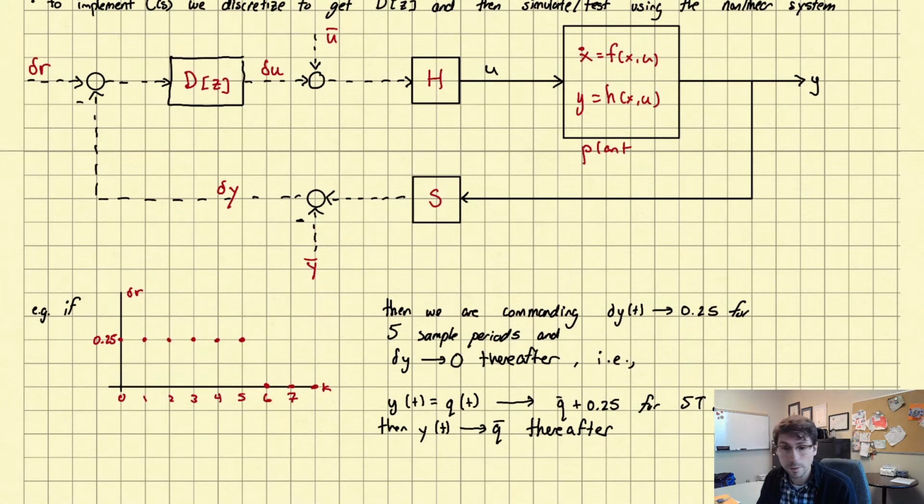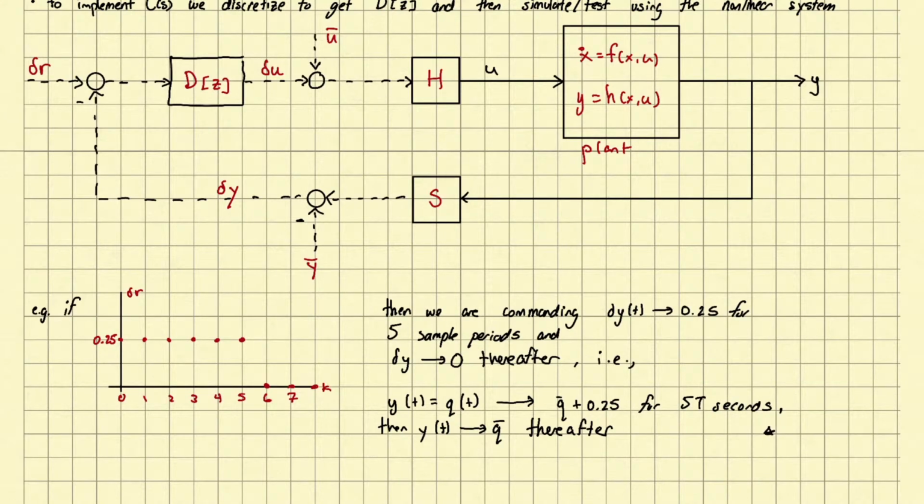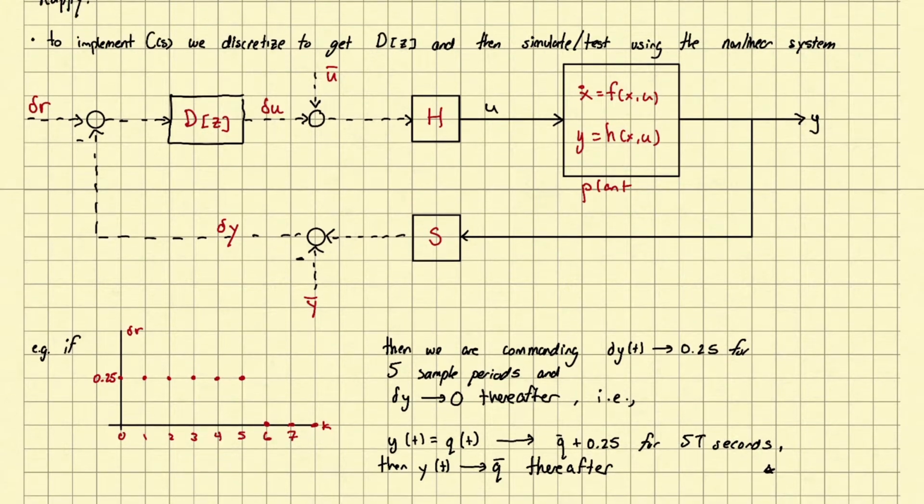Okay, so the subtle thing here is, keep in mind that after you've designed the controller for the linearization, you are commanding the deviation from equilibrium. Okay? And if you go too far from that equilibrium, if you command it too far, your linear approximation is not going to be very good anymore in general, and the controller might act unpredictably, right?